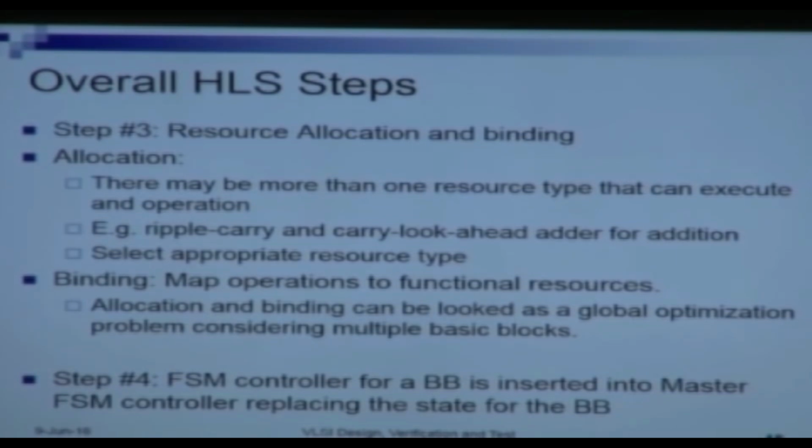Then binding comes, where we have to map operations to the functional units. So what we do is that we actually bind the functional units to the operations in the schedule. Allocation and binding can be looked at as a global optimization problem considering multiple basic blocks.